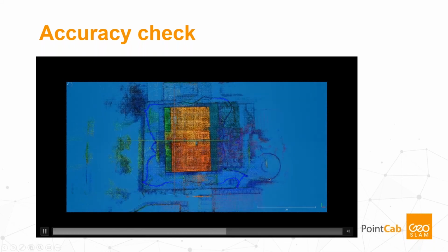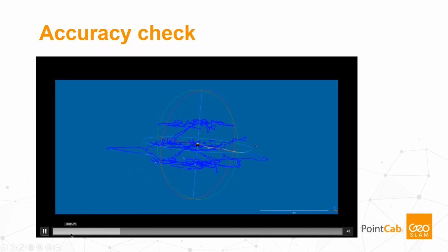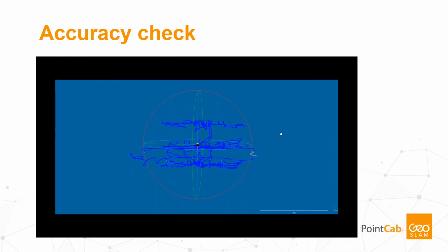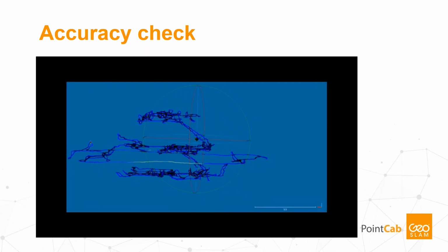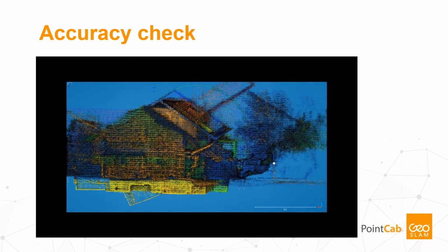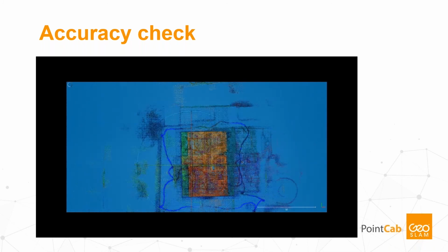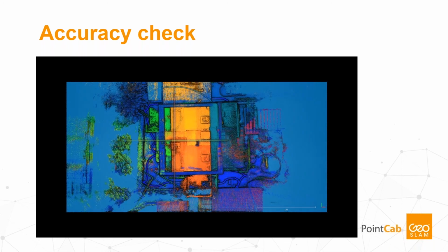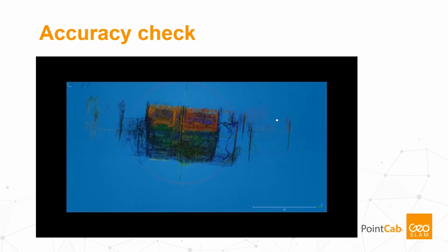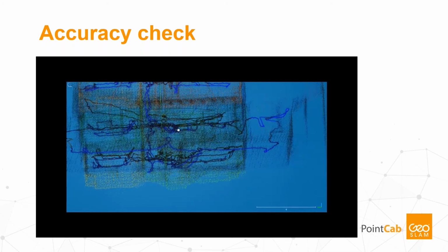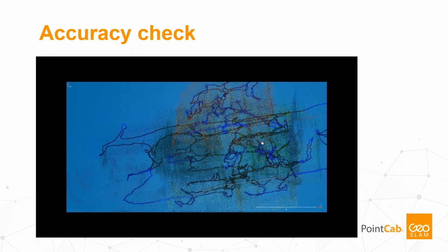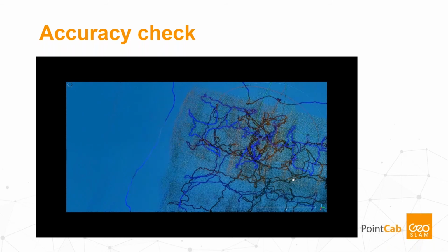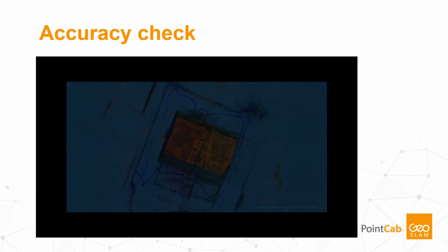And next, if I just move a little bit backwards, you can also see that only one staircase was available in this house. And saying that, to improve the accuracy, you can make use of the range of the system. If you start a scan outside first, then you can see a lot of features around. In each floor, if you have a balcony or a window where you could allow the system to see through, it will see the same features outside, trees, parked cars, and this way it will also count as a loop closure in case you don't have the multiple staircases available.